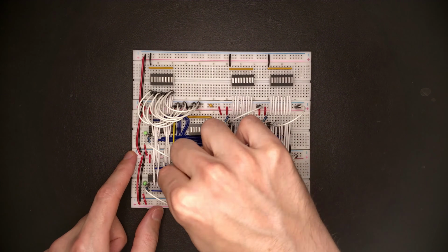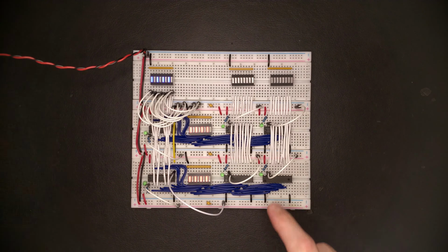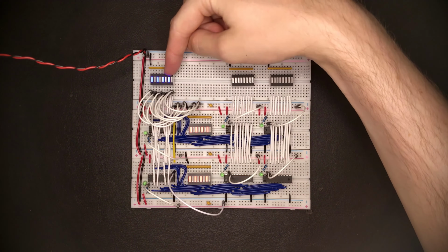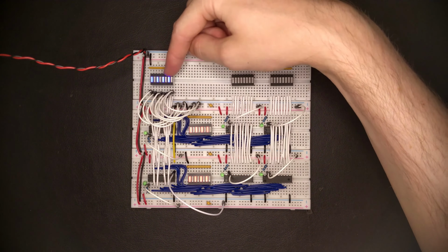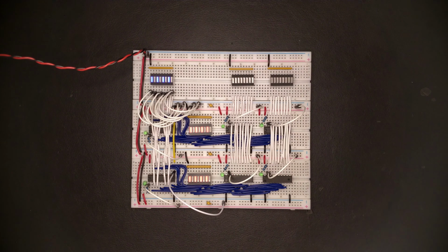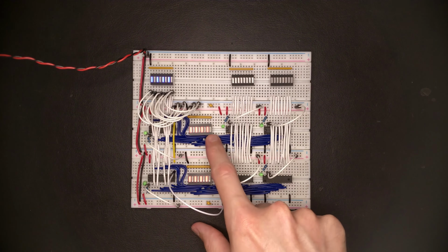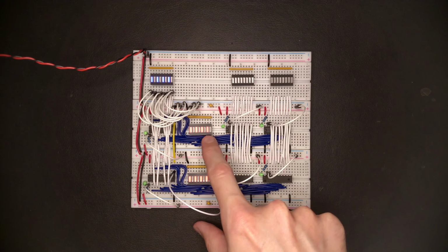And finally the clock. Let's power this up and see what happens. So we see the pattern of alternating bits here at the write data input to the register file, which is what we've configured with these wires here. And then during the power up sequence, because it's kind of like an arbitrary way how these initialize these registers, they already latched this pattern in.